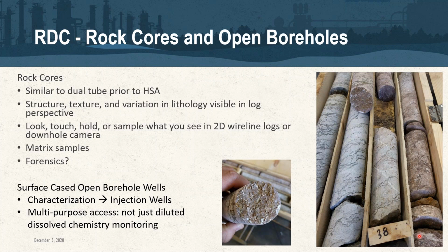So transitioning into what I want to talk about as importance for drilling considerations as well is getting into the character of the geology itself. As Derek had mentioned before, typically consolidated geology monitoring investigation points are installed with air rotary methods, where essentially the end process is simply to get a cased well in. But like he said, looking at rock chips coming from an air rotary hole, for instance, does give some indication of just general geology, but doesn't really tell us a whole lot of information about the actual nature and orientation of the geology itself.